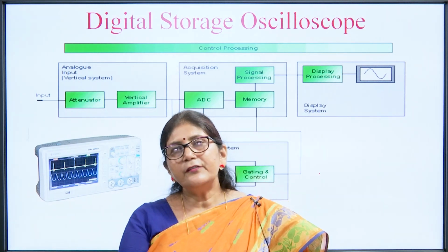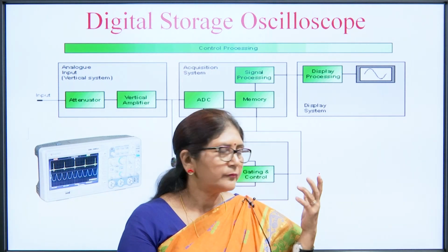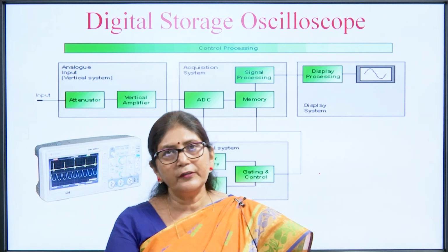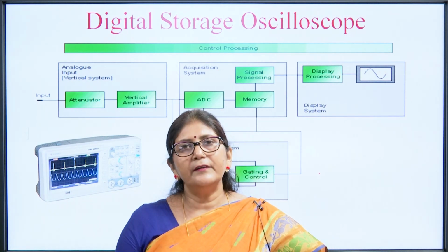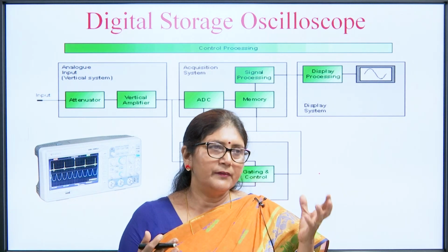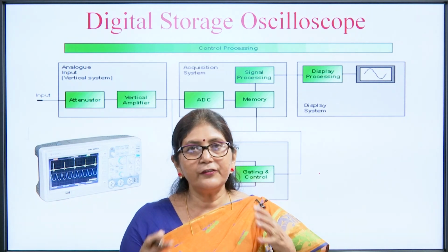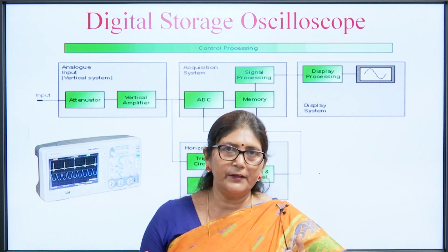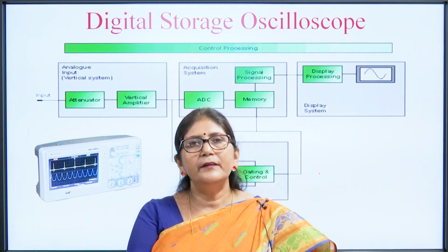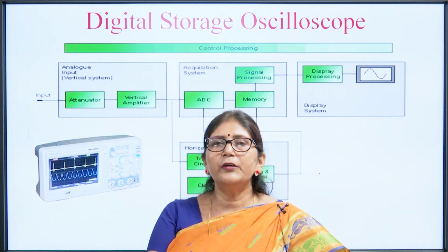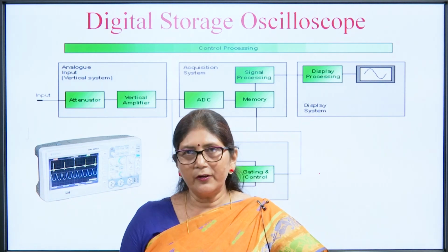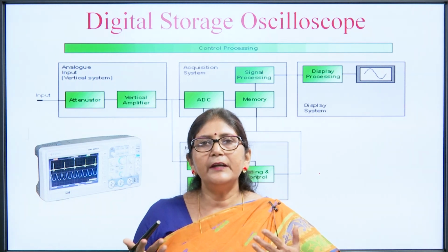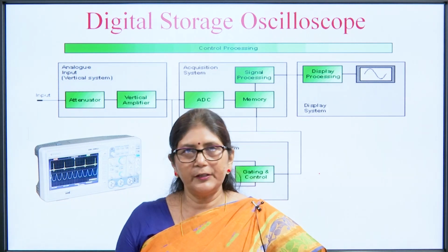Then next is the digital storage CRO. Analog storage CROs are not used today because they are very costly, and the configuration of that CRO is also very complicated. So, nowadays digital storage CROs are used, because in digital storage CROs we can store the data for a very long period of time, and it can be displayed whenever we require.